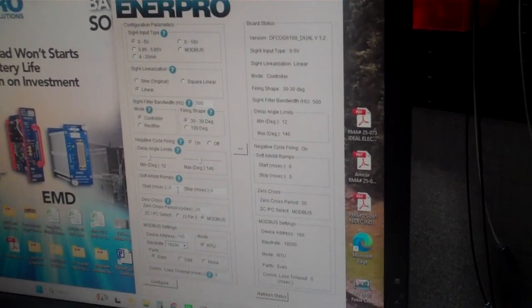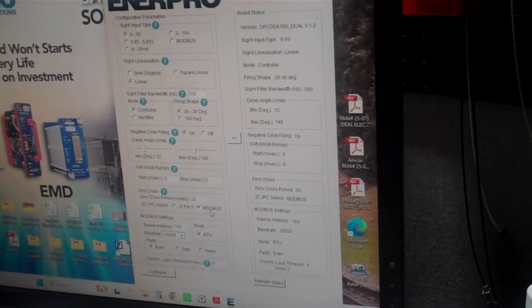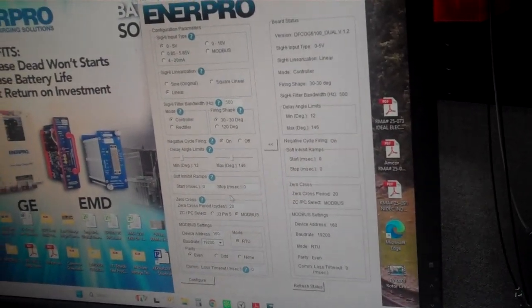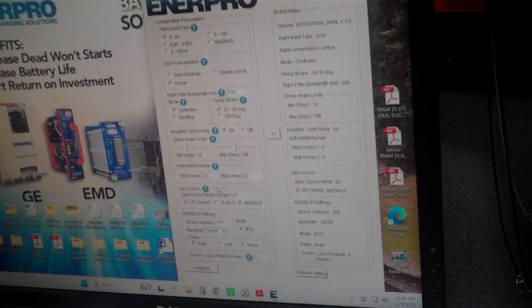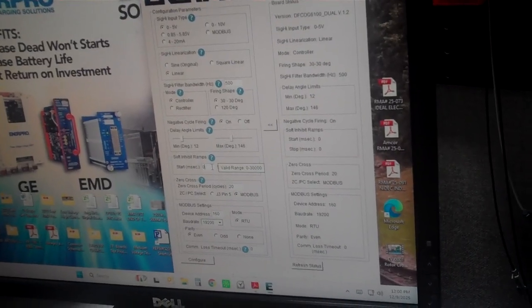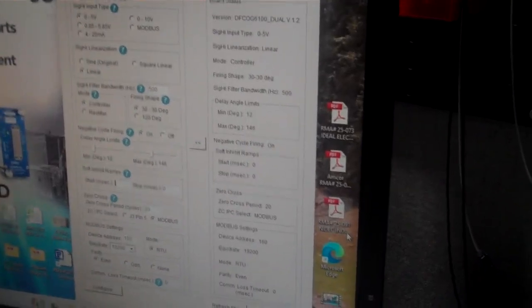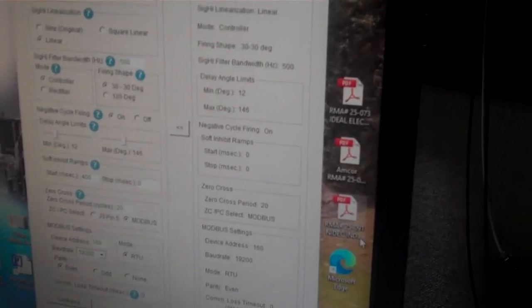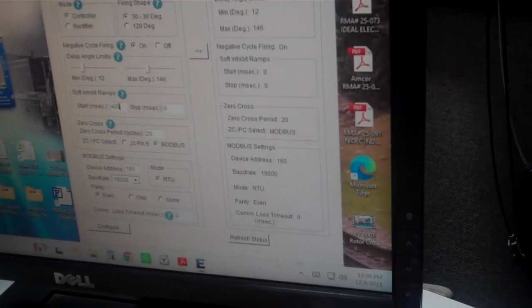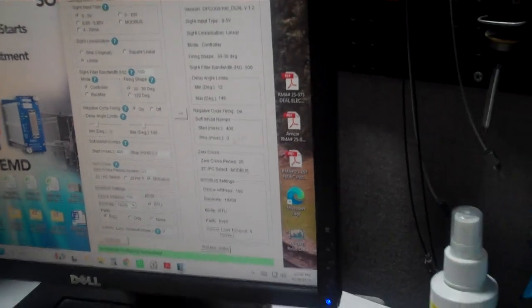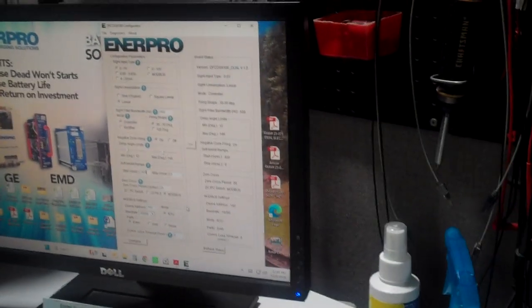We basically made the soft start inhibit an instant enable. We've eliminated the time. So just go ahead and give me, I don't know, 400 milliseconds, Tony, for the soft start. Can you go ahead and configure? And now we have that, and there it is. And we can always make changes.